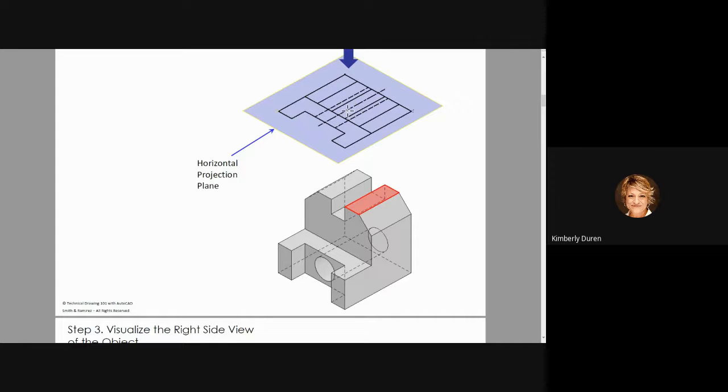You know, these breaks could be so small that they kind of look like hidden lines, but it doesn't stop at the edge of the material. It goes on. That shows me that's a center line. Edges stop at the edge of geometry where the material stops. So this is the hole, one side and the other, the full diameter, and this is the center axis. It goes all the way through.